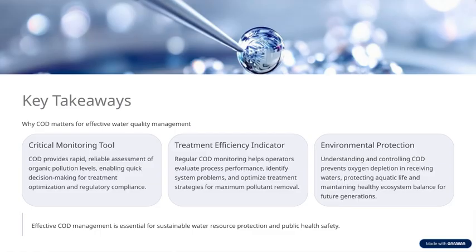Next, COD is an excellent indicator of treatment efficiency. By regularly monitoring it, operators can evaluate how well their systems are performing, identify any problems that may arise, and fine-tune strategies to maximize pollutant removal. This ongoing assessment is vital for maintaining high standards of water treatment.